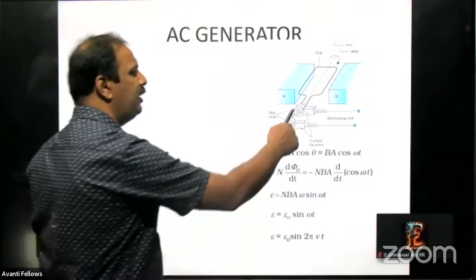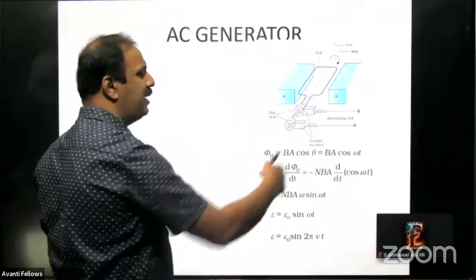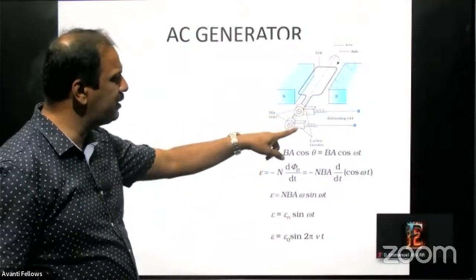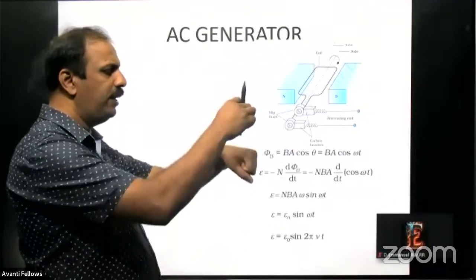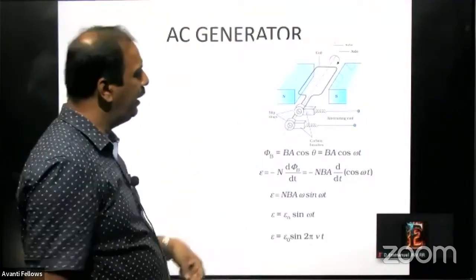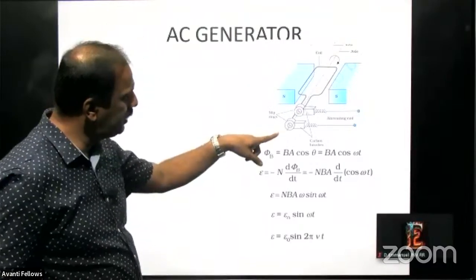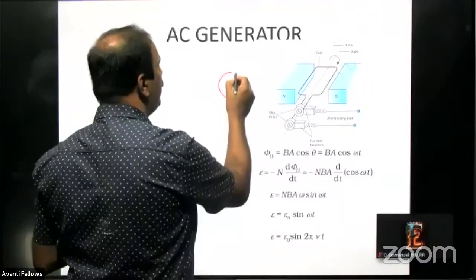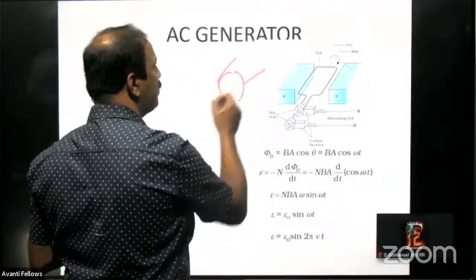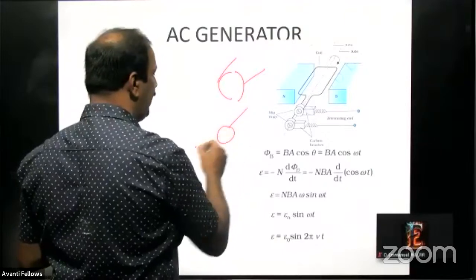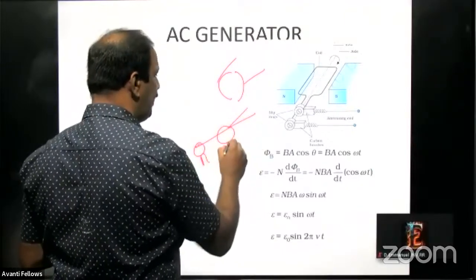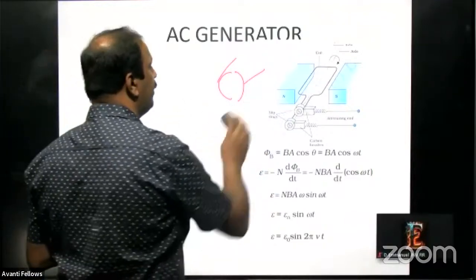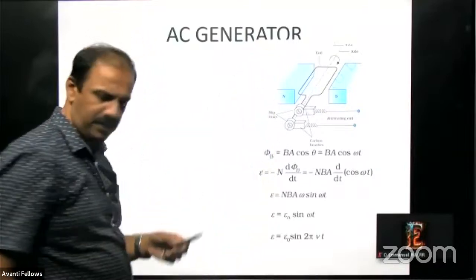And these things, you know, the slip rings. For AC generator, we will have two separate rings here. There will be a connection as long as it's sliding over that one. And this is opposite in the case of DC, where we will have a single ring splitting into two. That's called a split ring. We have it like this for DC, and in the case of AC, you have one ring like this and another ring like this, separate. In the case of DC, you have a single ring splitting like this. For motor and generator, it is both like that only.